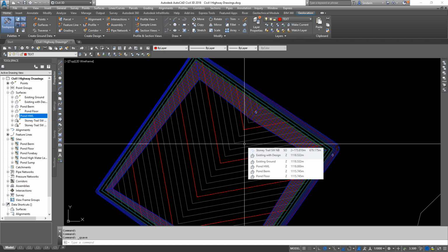Now the forebay is what holds your water. It's kind of the lowest part in the pond. It's where most of the dirt will settle if any dirt gets into it. It's easier to clean out just a 10 by 10 meter forebay than the entire bottom floor of your pond. And it'll be about half a meter to a meter lower than the rest of the pond, so they can pump it out easier. So all the water will flow into the forebay. It'll be the lowest part, and it will collect the majority of the dirt.